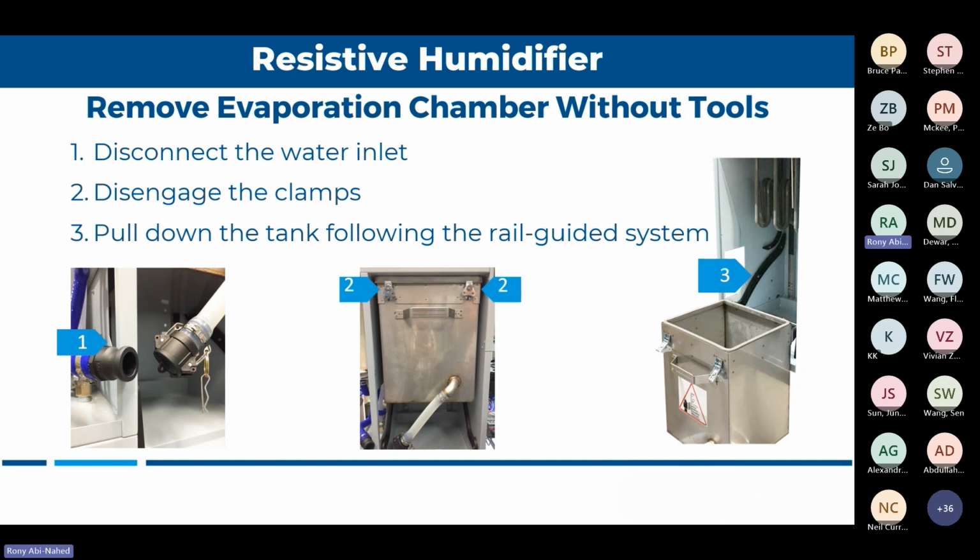I'll give you a quick example. We had a job at a painting booth at an automobile factory. The customer installed one of these units, the resistive ones, without an RO system. And he needed to run the unit the whole day because the painting process runs the whole day. And he started having trouble with the unit, like draining, and he's losing set points, and it's not good for the painting. So once I went on site, I saw what the application was. I explained to him that it was a wrong application, not having an RO system. You always need an RO system for these types of precise applications or long run applications where you can't stop the unit.